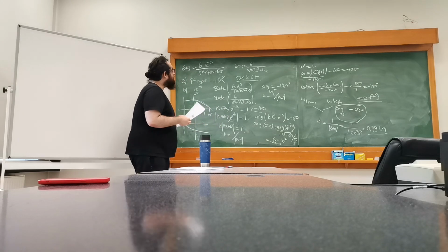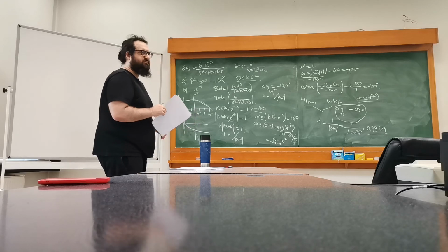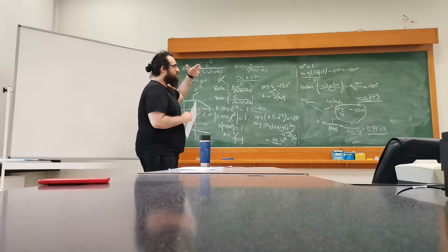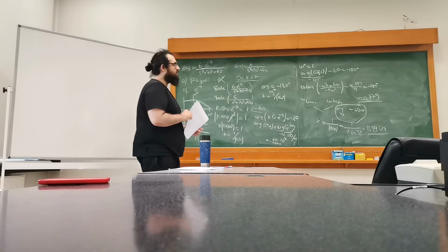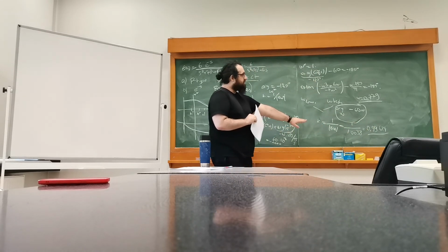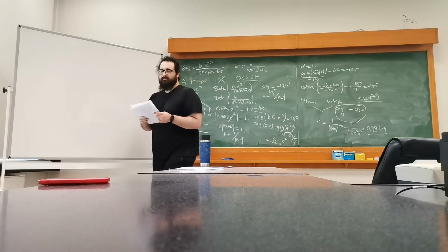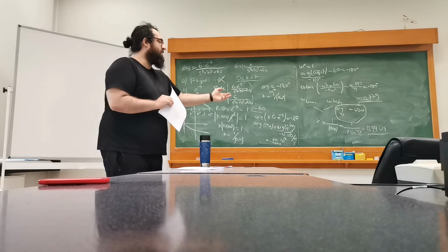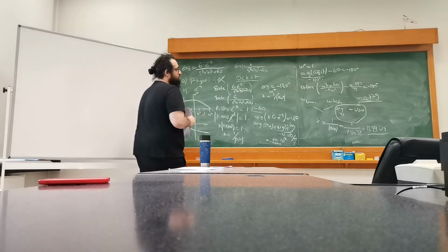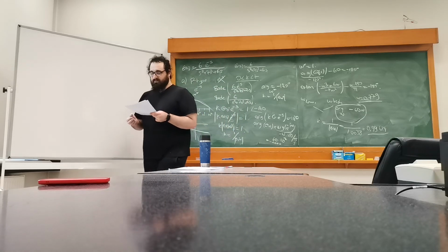So, if you remember, we had a design in the first question, I guess. We assumed that we can only have gain 1, and how much delay can we add to the system until it's marginally stable. The value of the delay was 0.99, but the gain value was equal to 1. So you can see that we have approximately that case here. It's a special case that is chosen here. So I have basically added 1 second of delay instead of 0.99, and then we see that the gain value should be 1.0038. So it's basically compatible with question 1 because it's basically the same system.